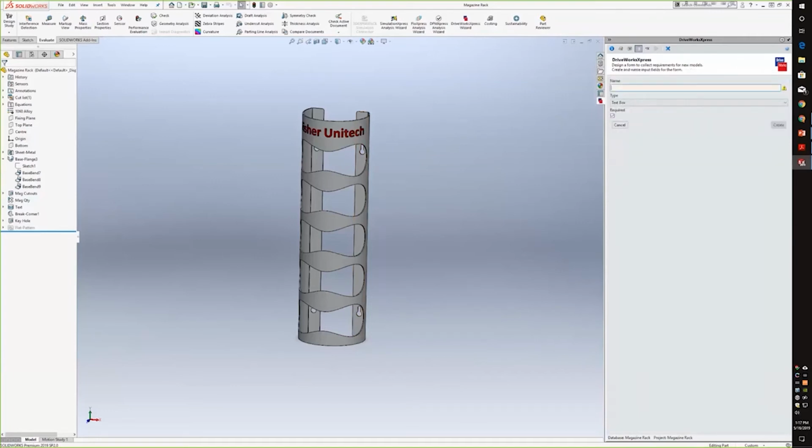Okay, and from there now we want to have an input for our captured values for our depth and width. So I'll go ahead and do a numeric text box here. Go ahead and call this depth. It'll be required, and now I can actually enter a minimum and maximum value. So instead of having the customer or maybe the engineer type in just some arbitrary value, we do want to have a bound to it. So in this case, for the depth, I'll go ahead and set a minimum of 150 and a maximum of 250.